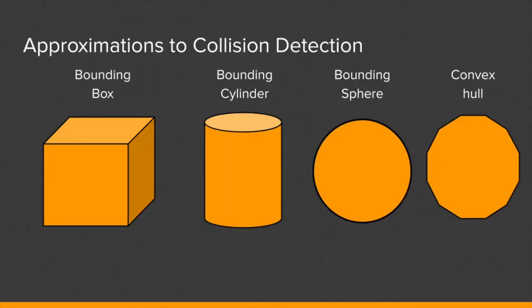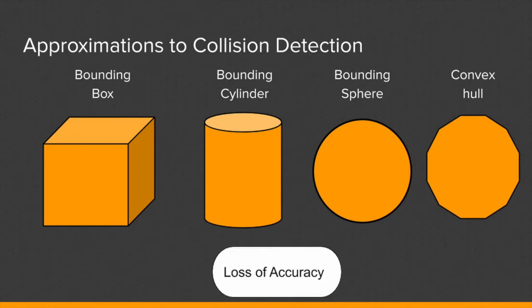Many approaches use geometric volumes to model the robot and detect collisions between objects. Models such as bounding spheres, axis-aligned bounding boxes, oriented bounding boxes, and bounding cylinders are used as an abstraction of the robot's true model and provide fast approximations. However, they achieve this at the expense of conserving the true form of the robot, losing the ability to get the true distances between objects.